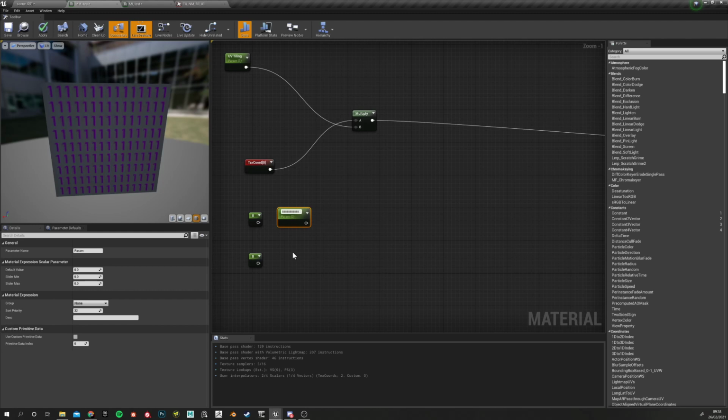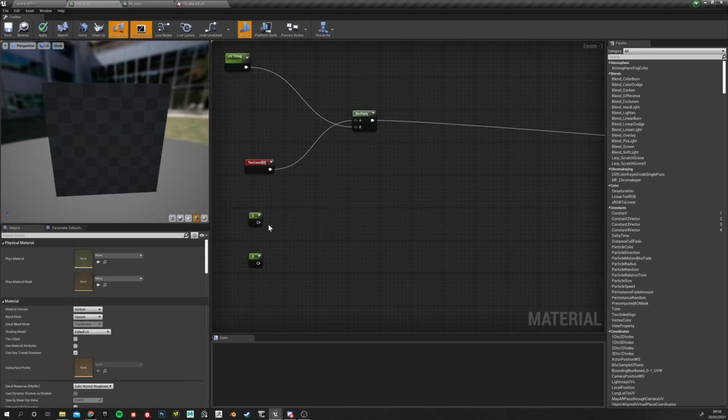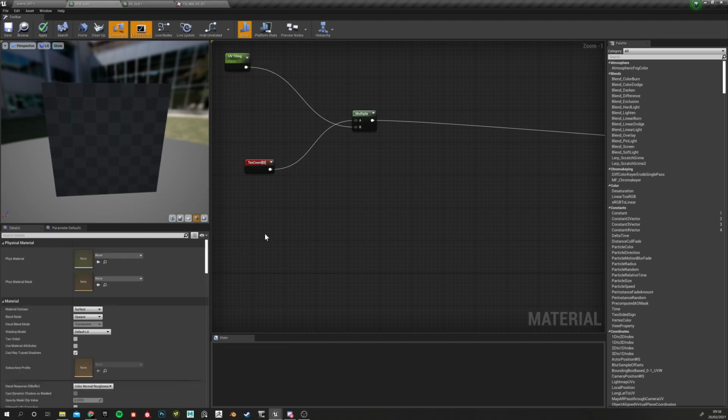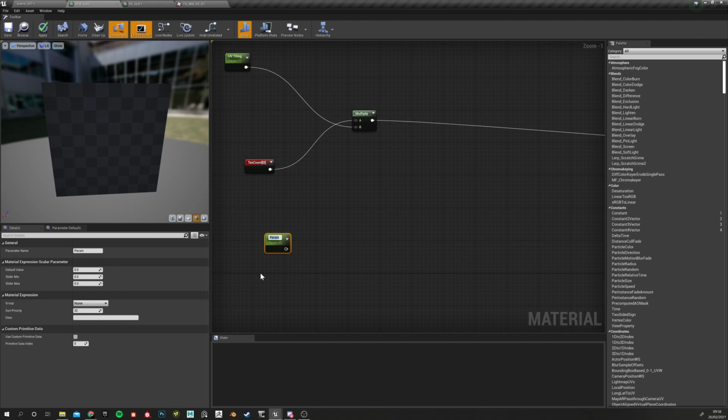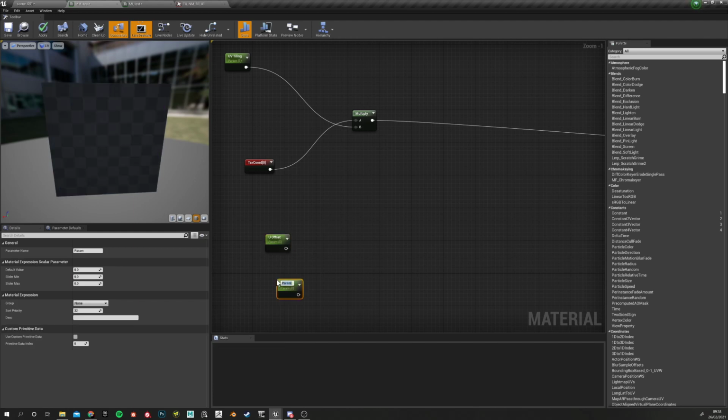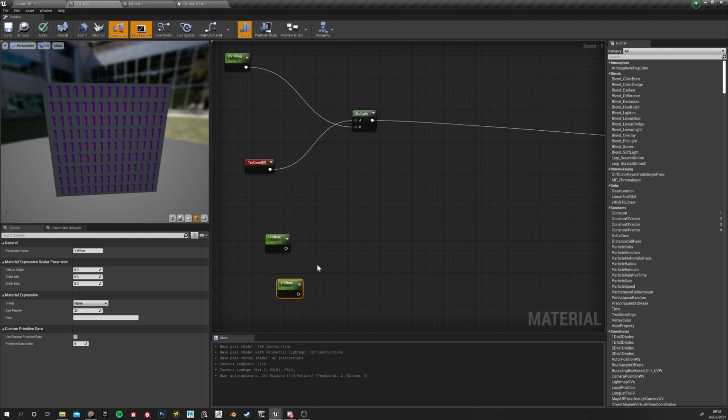That will be a scalar, which is a simple number, and then you turn it into an actual parameter. You save one step if you do that. So this time, instead of pressing 1 and click, we just press S and click, because we know we're going to turn this into a parameter. This one is going to be called U offset. Then we press S and click again, and we're going to call this one V offset.